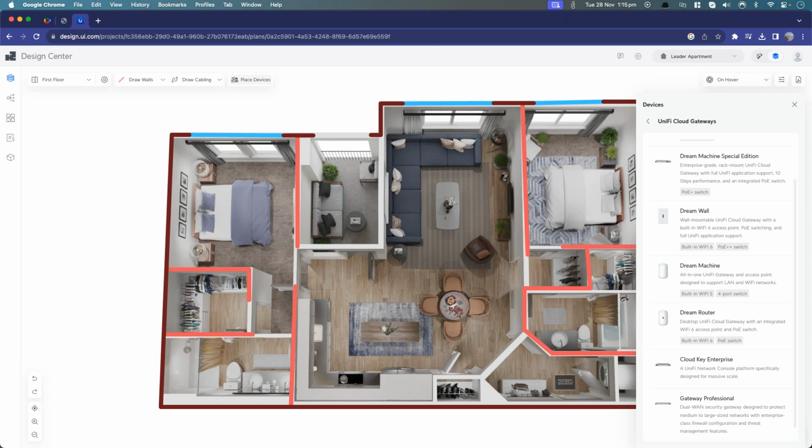So it depends on the use case, I think. It is 100% a good idea to possibly draw in the doors as walls as well. If you do that, I would just draw it in as a drywall or even possibly glass. The main thing we're trying to achieve through this is a lower level of attenuation, and glass has a fairly low level of attenuation. So if you're adding this in, it should more accurately represent it that way, but it depends. Do you expect the door to be normally open or normally closed? It's really difficult to try and design for that, but up to you to make that call.